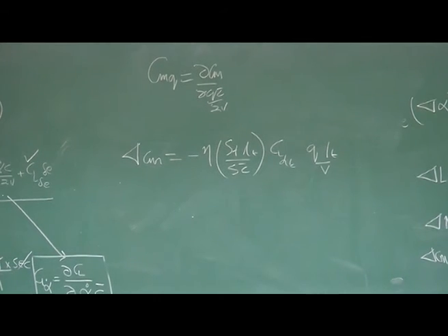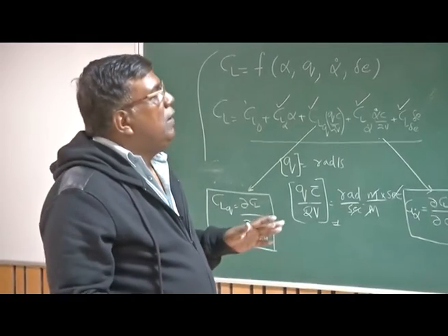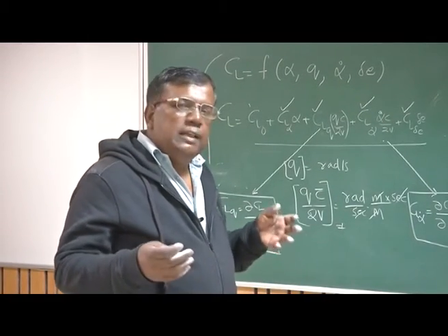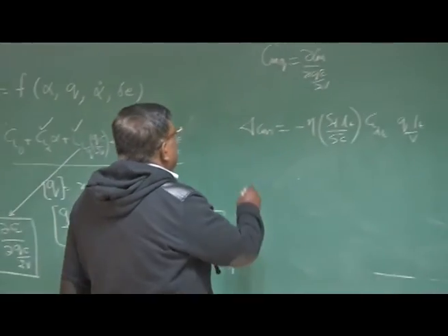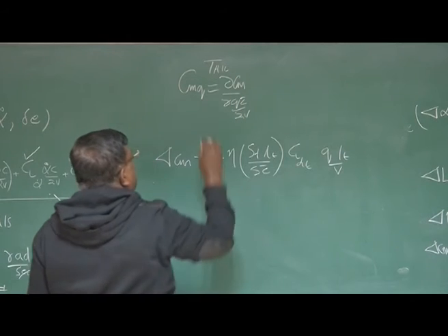We have to similarly find out the contribution because of fuselage and wing. But we are trying to find first the expression for tail contribution, because we know that is the primary component which will add to these derivatives. So again, we are now focusing on the horizontal tail.